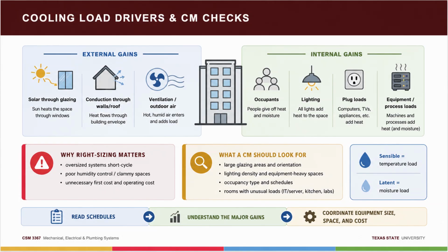And know that when the mechanical engineer starts talking wet bulb temperature, they're talking about the latent side of the problem. Dry bulb is the regular thermometer temperature, the sensible side. Wet bulb bundles in the moisture. Quiz alert. Dry bulb temperature equals ordinary air temperature, sensible side. Wet bulb accounts for moisture, latent side. Psychrometrics equals the study of air and moisture mixtures.